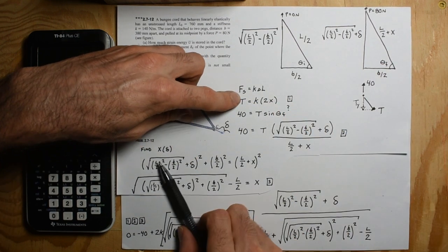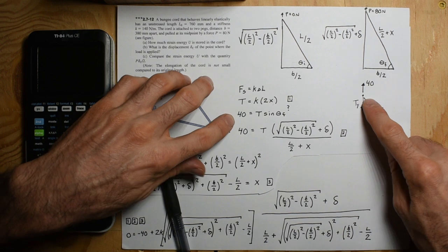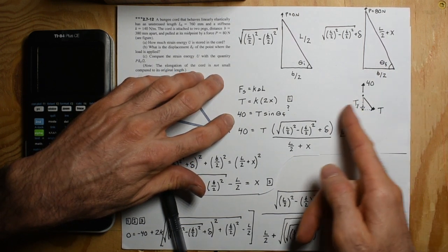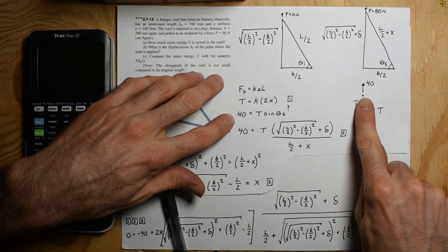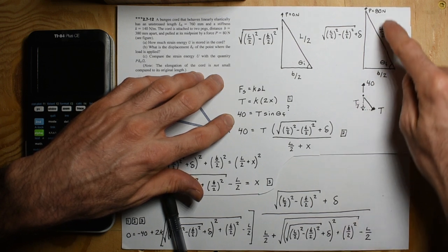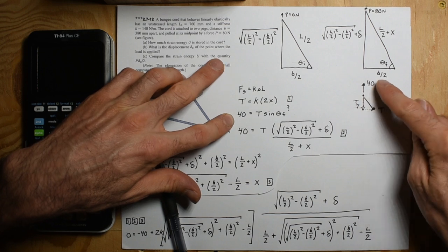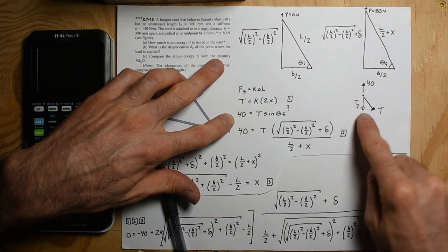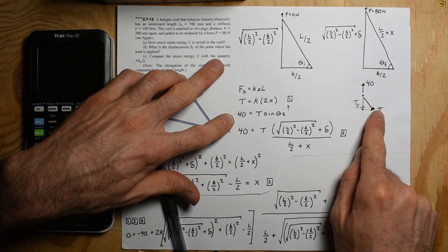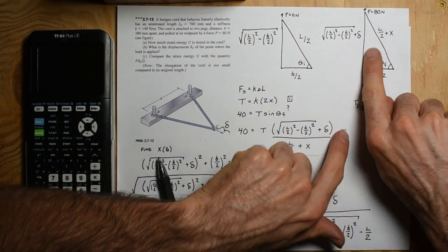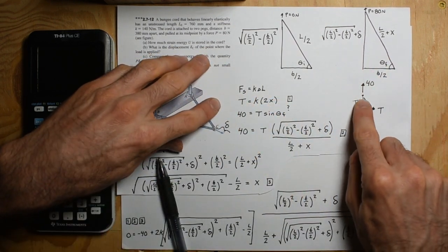That's our first equation. Now, when we set up the free body diagram, I'm just going to choose a side. We know the forces are balanced, but I'm going to say P divided by 2 is 40. They wanted 80 for the problem, but if you just take one of the tensions, we're saying 40 is equal to this vertical component. Obviously the other tension will balance and it'll be 80. But we just want this vertical component.